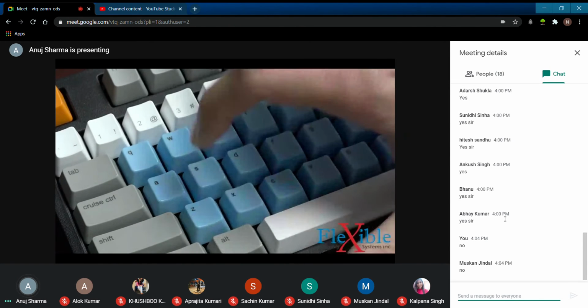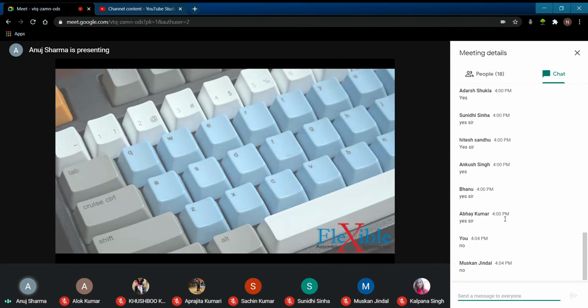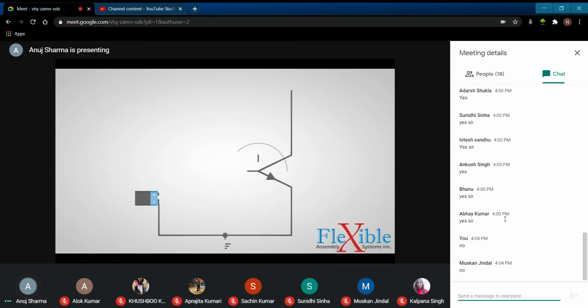The state of the switch is changed momentarily while actuated. On top of deciding between normally open and normally closed, you must also decide between an NPN or a PNP transistor. These control the current flow within the sensor. This diagram shows a basic NPN transistor in a circuit.